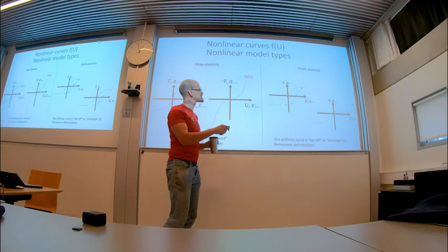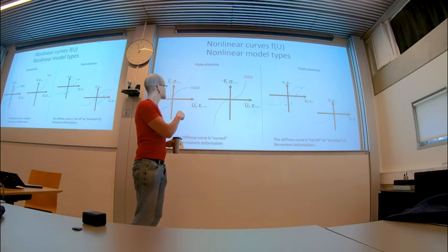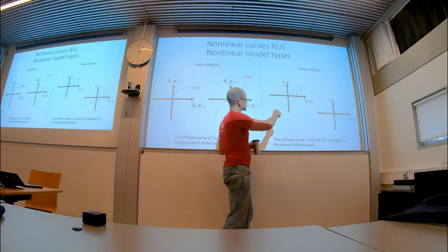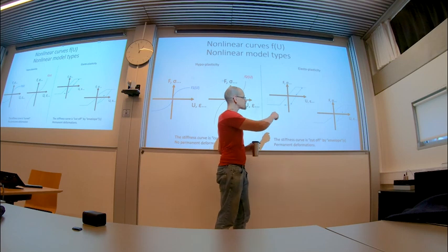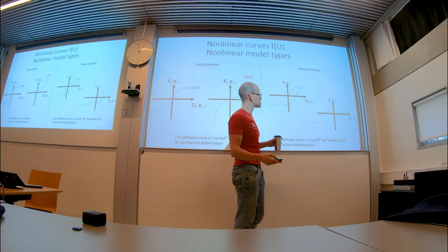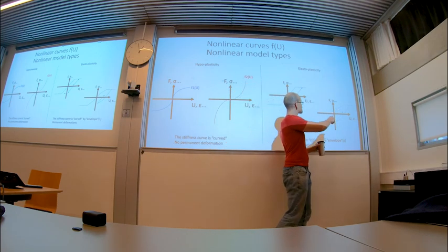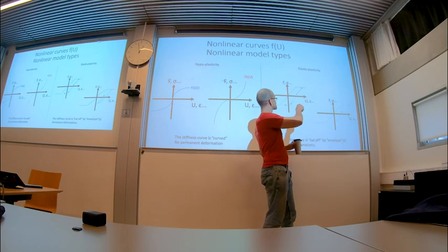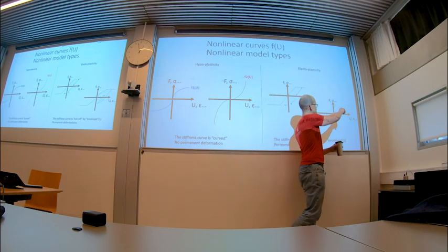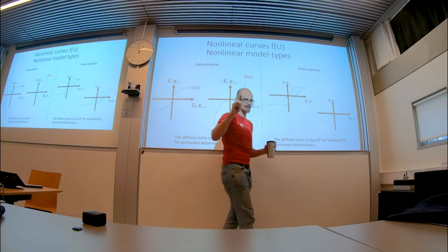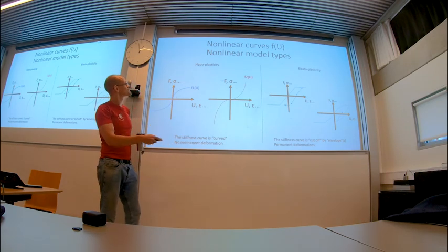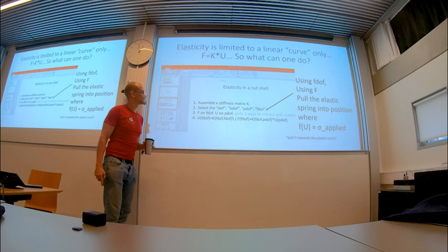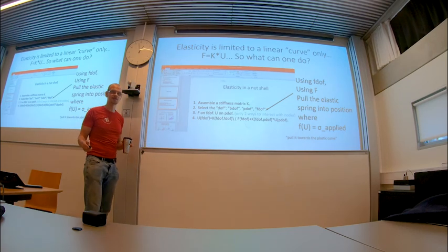And in elasto-plasticity, normally, it's pretty hard to have smooth curves. You usually have this kind of shifting of the stiffness path back and forward. Then the casual method of dealing with it is to add more yield surfaces. So some different plastic increment starts from here, and from there it is just flat. And then if you unload, you go through the envelopes, you will get that in the next lectures. And that's elasto-plasticity, that's hypoplasticity. But there's a very small difference between them.